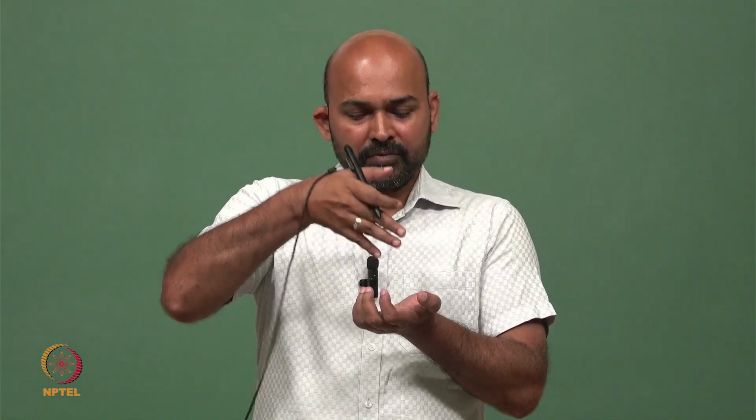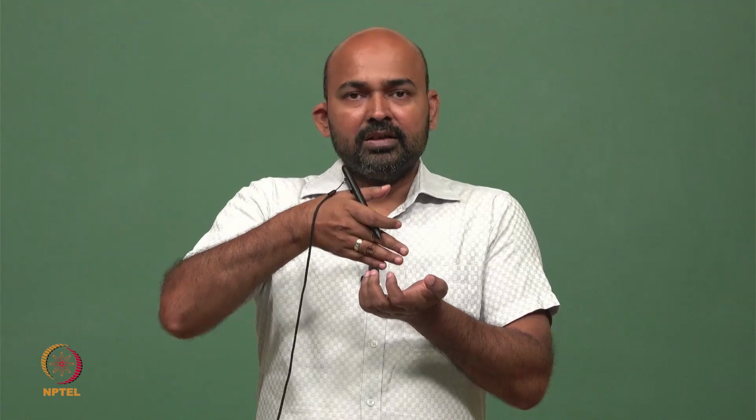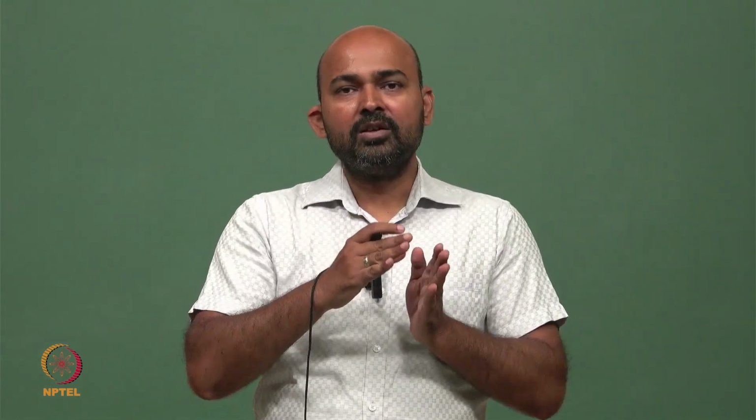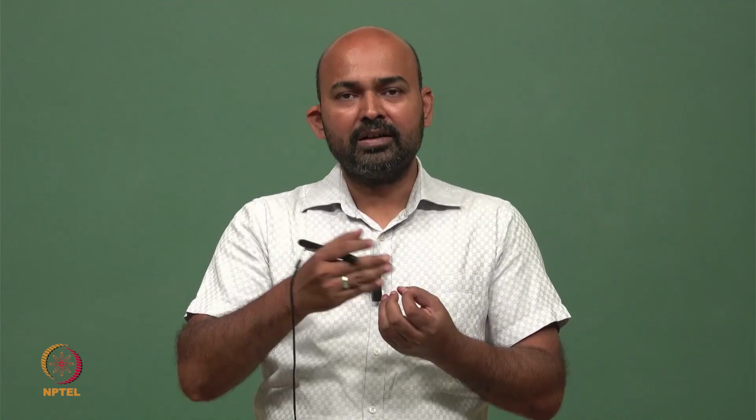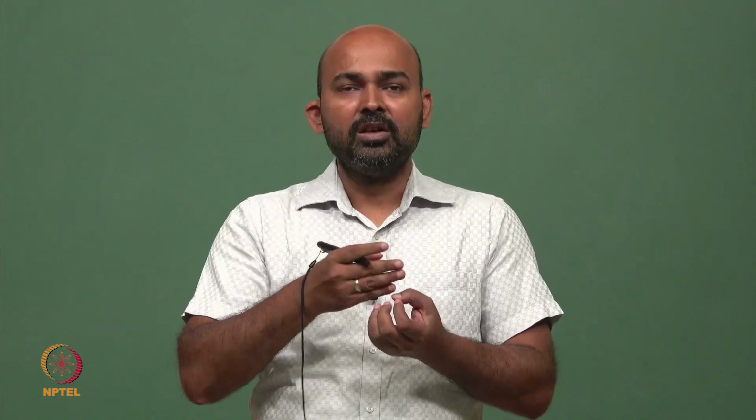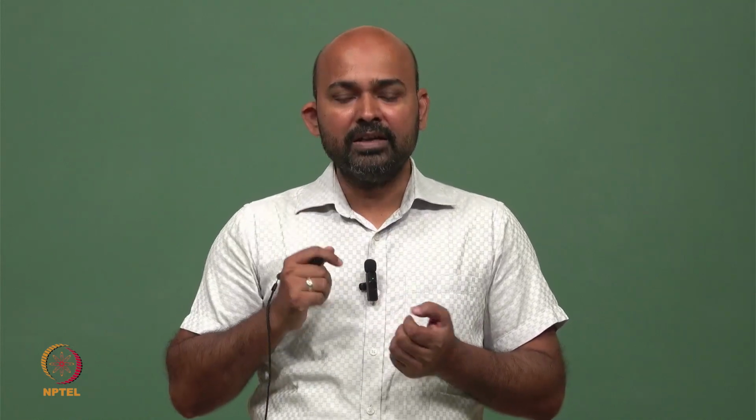We bond them on the surface. These fins have little volume, but the surface area of these fins is very high, so that they are in contact with so much air, and the air will take away the excessive heat from these fins. So the fins are used to increase the surface area of the heat sink.